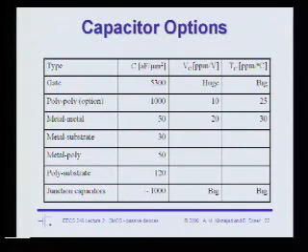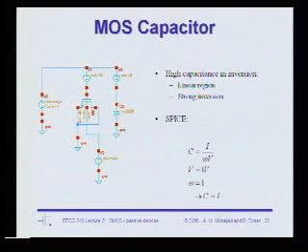So what I'm going to say here applies pretty generally. Let's just go through a little bit. So here's a MOS capacitor. If you want to simulate a MOS capacitor in SPICE, here's a very simple way to do it. One way is to actually access the device parameters. You can go in and plot the CGS of the device, C gate to drain, C gate to body, add them all up, and that's your total capacitance.